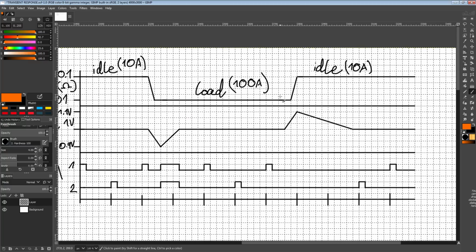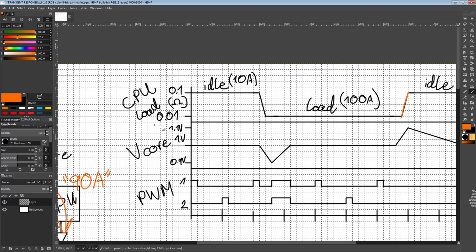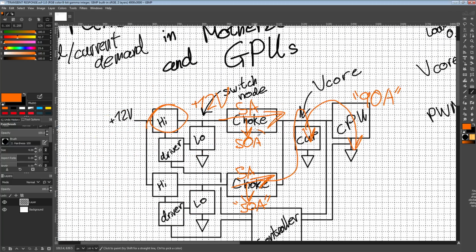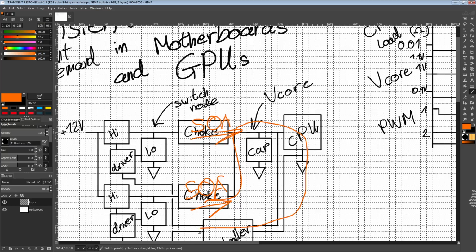And then eventually our CPU stops doing whatever it is that it's doing, and it goes from very low resistance back up to just low resistance. Now we have the opposite issue, because we've just charged up our inductors to push 50 amps through them, and they really want to keep pushing 50 amps through no matter what. So let me just erase all of this. Right, so now we have our 50 amps flowing through each of our inductors, and during steady state, we'd have that just flowing through the CPU and everything would be golden.